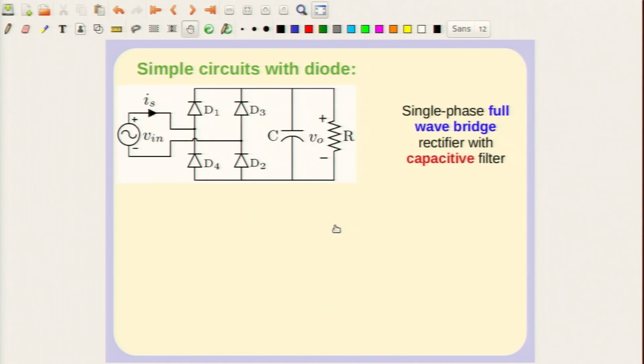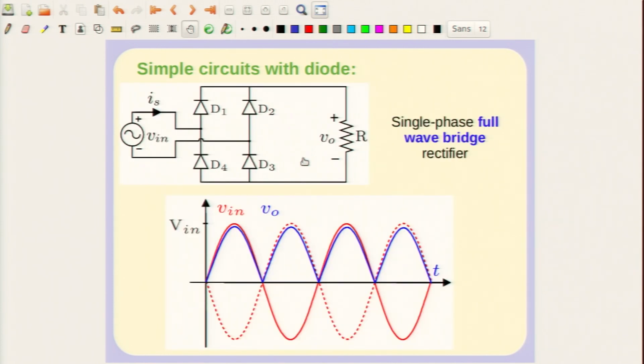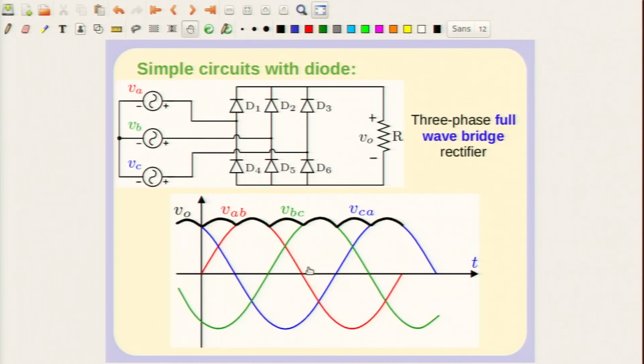We also have a voltage rectifier where, usually if you put a capacitor at the output, you can actually hold the voltage for some additional time. For example, if you go back, we will just go back a few slides and look at our full wave bridge rectifier. Here the voltage at the DC side follows the AC side voltage, but if you have got a 3-phase bridge rectifier, of course, you find that you have got a nice ripple free, rather not ripple free, but low ripple kind of DC voltage waveform on the DC side.